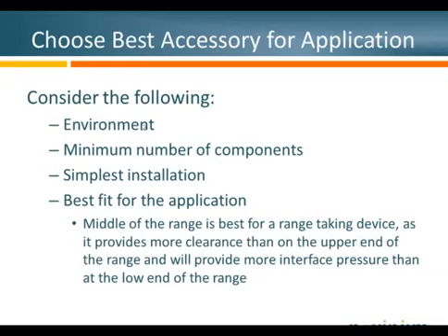So if you're choosing the best accessory, consider the following. The environment is critical. You have to consider that if you're looking for a live front termination. If you're going to put one next to a concrete plant versus out in an area where there's no contamination, or if you're putting one in a coastal area versus an inland area, those things are very significant.